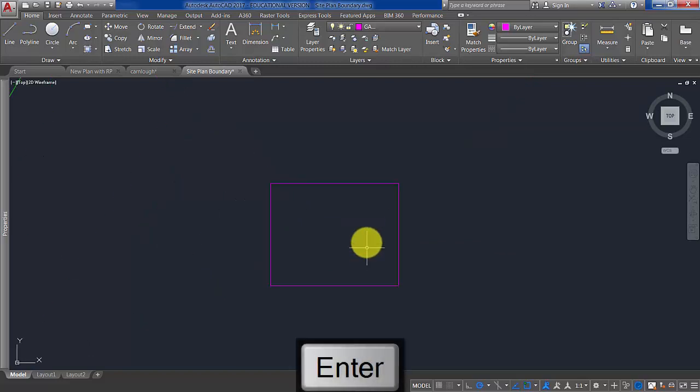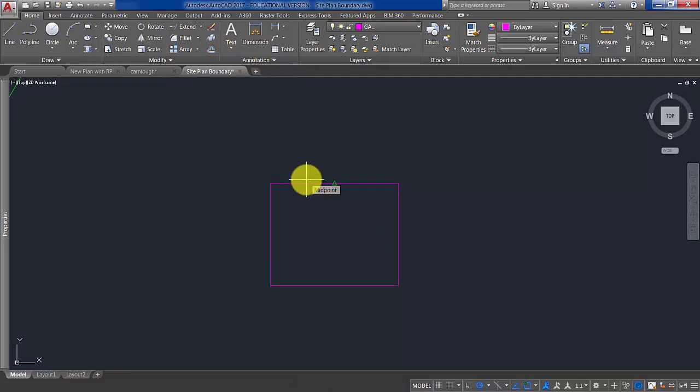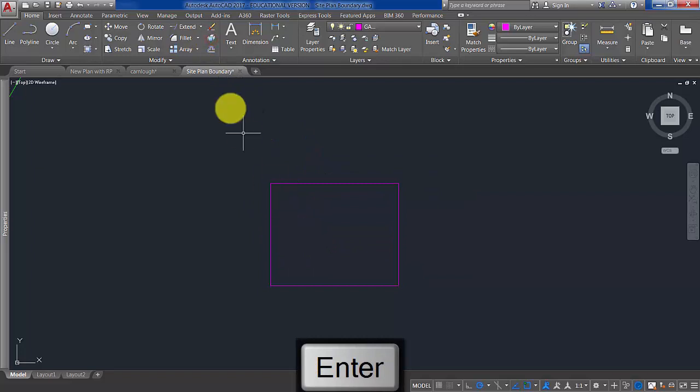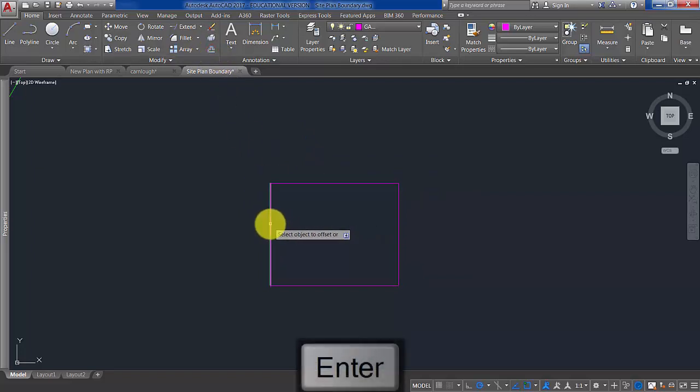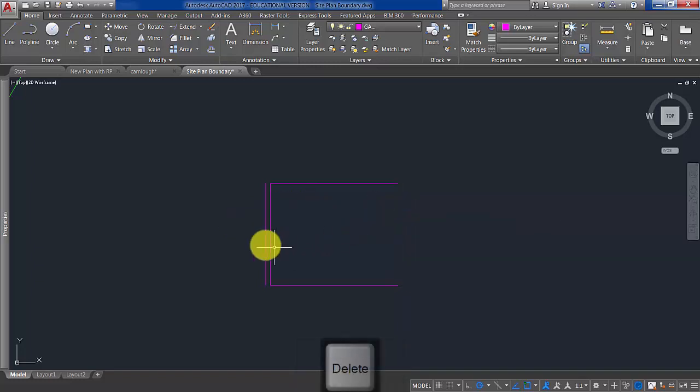Okay, and then we'll explode that and just start adding in the dimensions. So the outside wall is 400mm thick. Let's just explode that. Yep, offset 400. And we'll delete that, and once we have it fixed we can mirror it over to the other side.